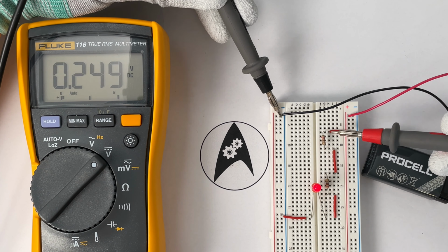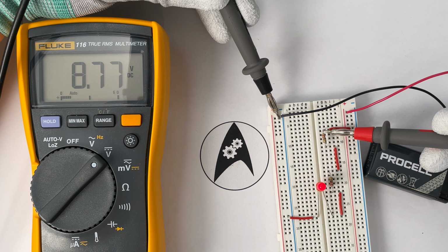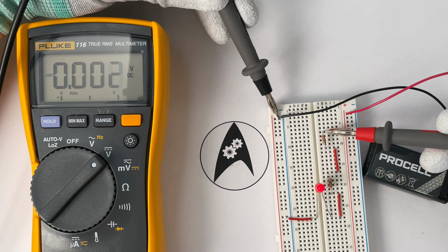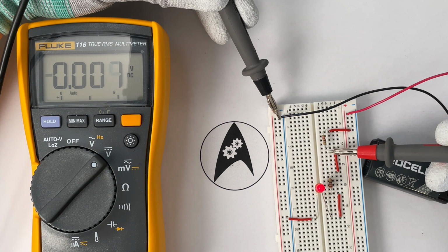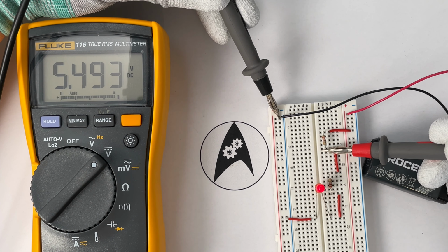When I move down, let's say to the beginning of the first resistor, you can see that the potential has decreased a little bit to 8.77 volts, so minus 0.02 volts, which is not much, but in the path from the positive terminal to this resistor here, nothing much has happened, and the resistance of the parts in between is very, very low. But as soon as I move the measurement tip against this resistor here, you can see that the potential now has dropped significantly, down from almost 9 volts to 5.5 volts roughly. So the electrons have lost potential energy.